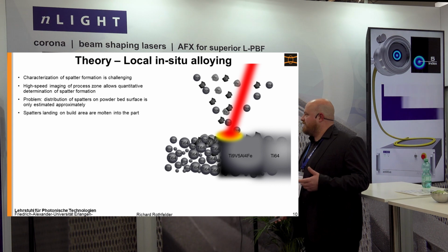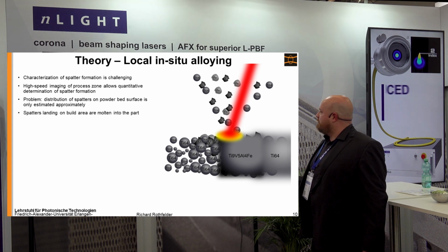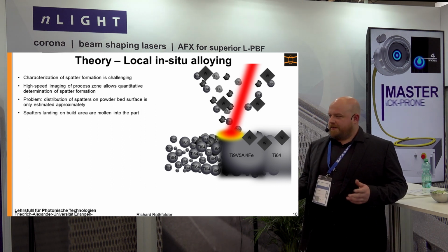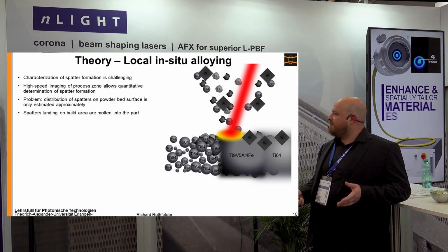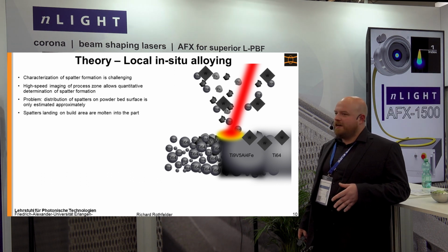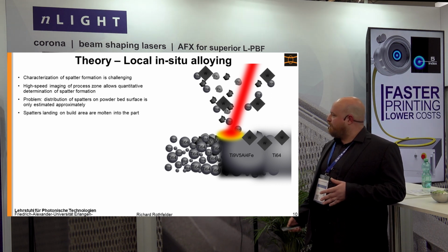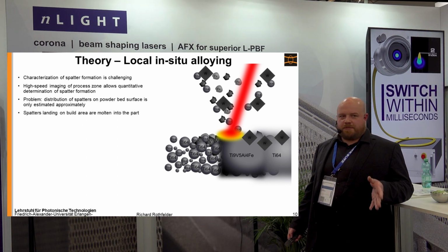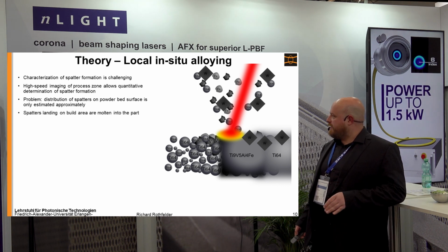But it's very hard to trace very little amounts of vanadium or iron in your then again mixed powder with the titanium. So we added tungsten particles. Why tungsten? Tungsten is extremely dense and has an extremely high melting temperature. So with the parameters we use for Ti64 and the base alloy, we will not melt it completely, so it won't get into any kind of alloy. It will more form a metal matrix composite. And when it lands on the surface, even on another part, we will be able by cross-section just to count the amount of spatter particles we find there.